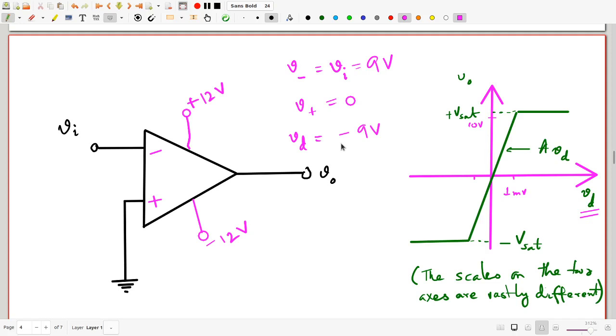Now what good would such a circuit do? Well, one answer which I often get when I ask this question to students is that this will provide a constant voltage supply, a voltage supply fixed at minus 12 volts. But that actually is quite wrong. As you must realize, the only reason that the output is fixed at minus 12 volts or somewhere close to that is really because the power supply is at minus 12 volts. If this power supply were to fluctuate, so would minus Vsat. So the only reason the output voltage is fixed is because the power supply is fixed.